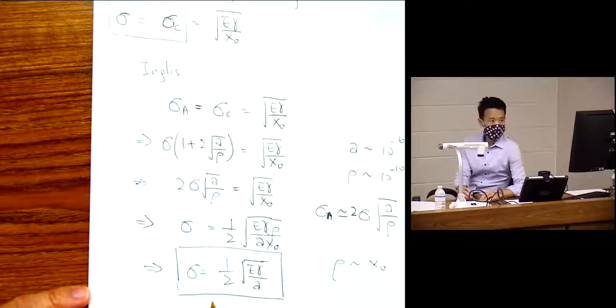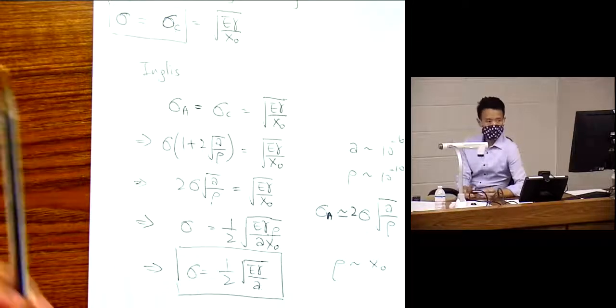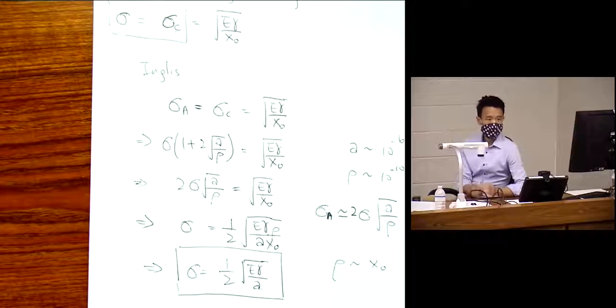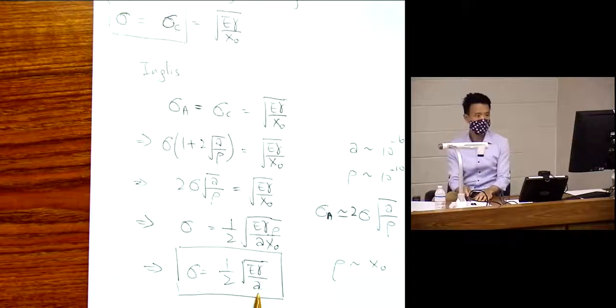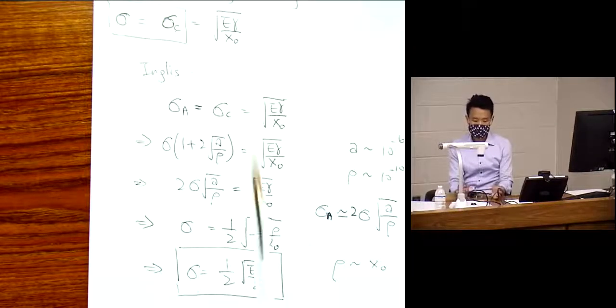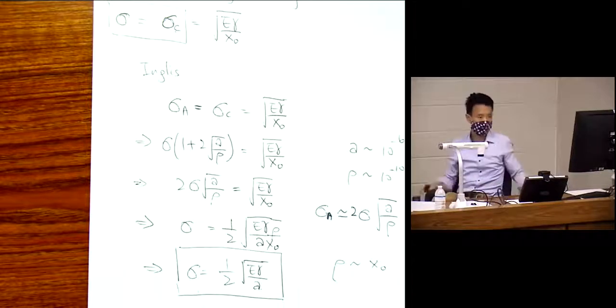Now let's come to the improved one, which we now know. It does not depend on the atomic dimension anymore. Instead, there is one more dependence, which is on the crack length. So this is, again, what we can measure. But instead of taking the atomic dimension of the solid, you have to measure the flaw size of the sample. You still need the surface energy of the material, but instead of the atomic dimension, this is replaced by the crack length, A.